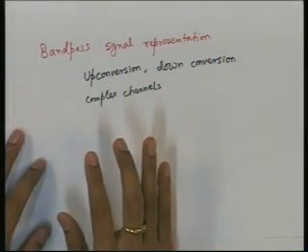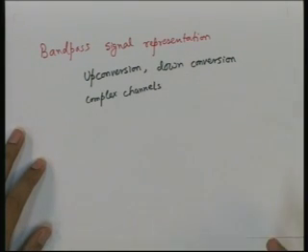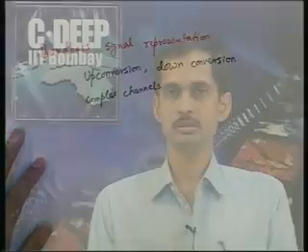So we saw how we can process the signal at the transmitter in baseband and then do up conversion, and at the receiver we can do down conversion to bring the received passband signal back to baseband and then process the baseband signal. So in this process, the baseband equivalent, that is the low pass equivalent of a real band pass signal, becomes a complex signal, and that is why in the low pass equivalent, the signal becomes complex, and as a result the transmitter system as well as the receiver system has to deal with low pass but complex signals.